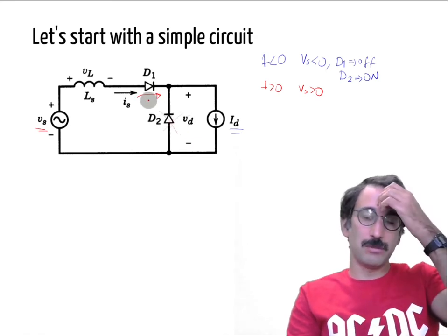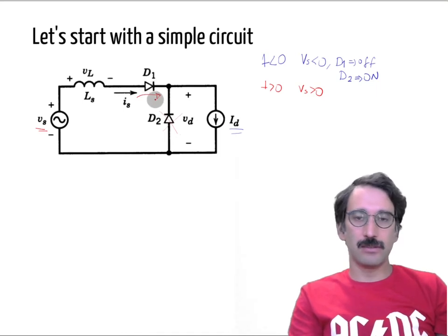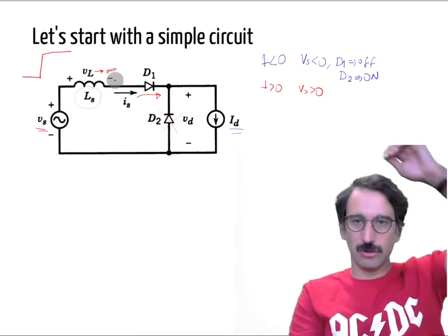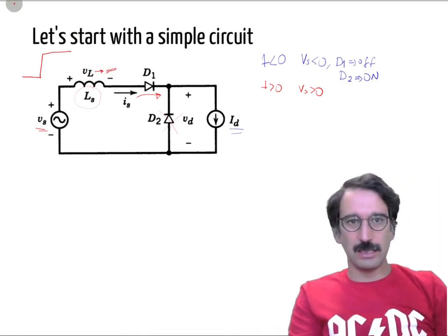But again, the problem is, if this happens instantaneously, from the inductor's point of view, D1 was off, so it was carrying no current, and after t larger than 0, D1 is on, so it will make a sharp rise, and again VL will go to infinite.